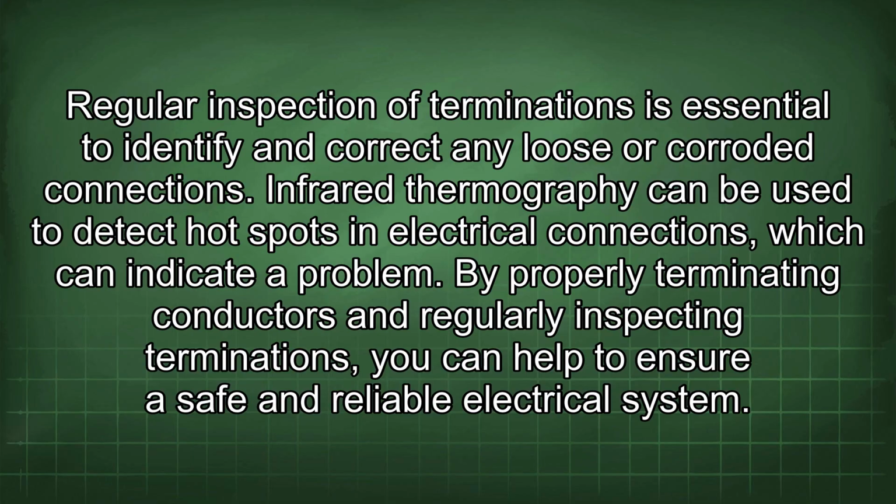Infrared thermography can be used to detect hot spots in electrical connections, which can indicate a problem. By properly terminating conductors and regularly inspecting terminations, you can help to ensure a safe and reliable electrical system.